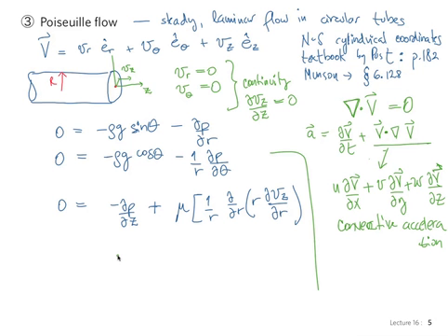Yes? So then steady is dV/dt equals 0, and laminar is del dot V equals 0. Yeah. This is 0 in the steady case flow. This being equal to 0 is not exactly equivalent to laminar. It is in the case of flow in a straight line, but the flow could be laminar and be kind of sinuous as well, and then you would have some sort of acceleration because remember the v is a vector. So if v changes direction, then this guy is not 0.